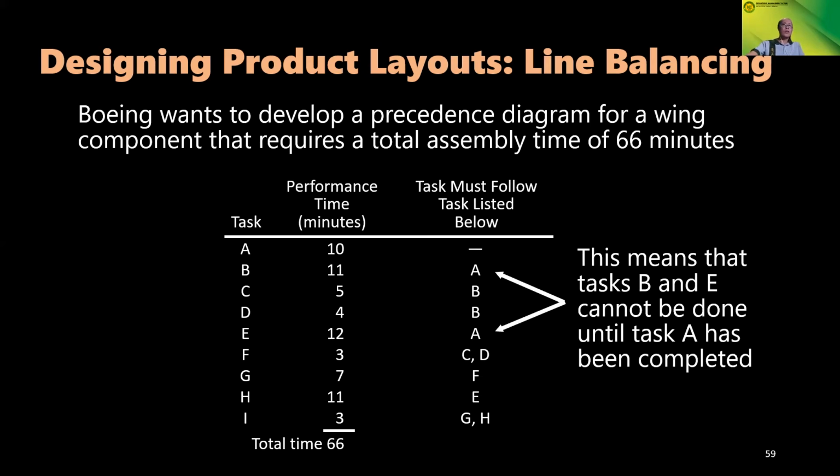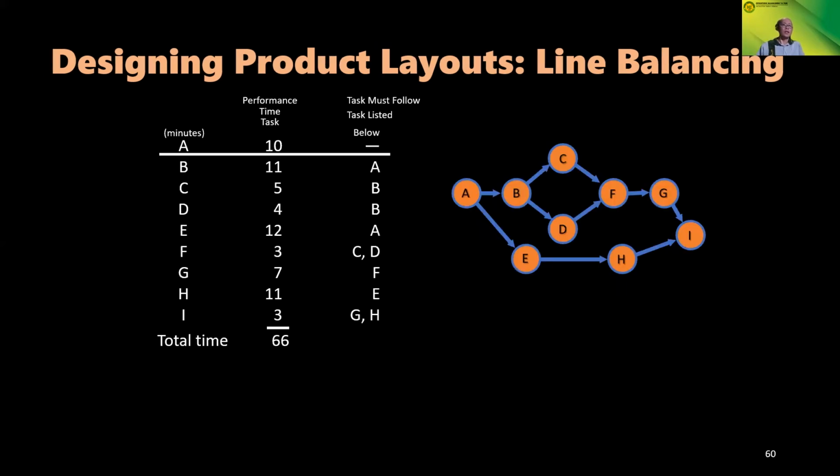Okay. So ang first step sa line balancing is to group tasks into job stations to meet the specified production rate in the form of a precedence diagram. This diagram helps structure an assembly line and workstation and makes it easier to visualize the sequence of tasks.